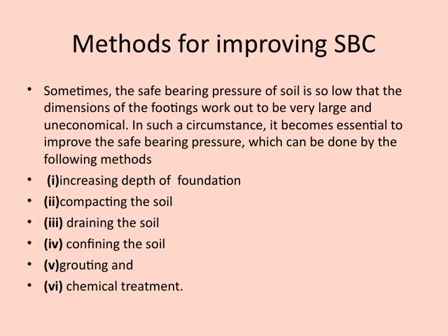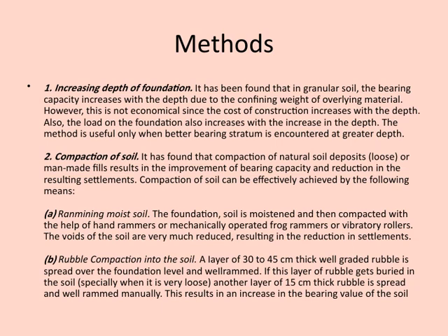economy of our structures. Let's now look at some methods to improve the foundation's bearing capacity. First, increasing the depth of the foundation can help. In granular soils, it's been observed that the bearing capacity tends to rise as you go deeper, mainly because of the overlying weight providing more confining pressure.